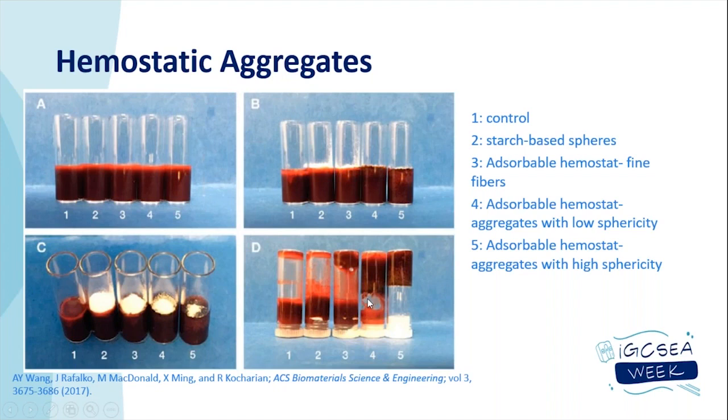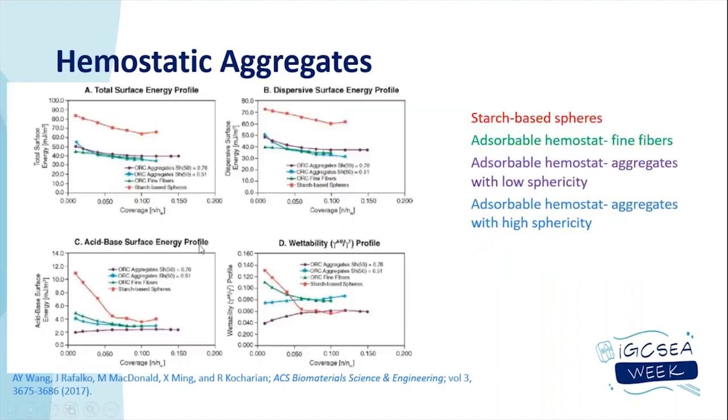So we want to look at the surface energy values of these materials, and it's a little bit busy. If you want the full details, here is the reference for this paper. But again, for these starch-based spheres, if we look at the total surface energy and the acid-base surface energy, the acid-base contribution is much higher. So these are very hydrophilic, whereas in the other samples, in particular the samples with high sphericity, we see a lower acid-base contribution, meaning that these might be more lipophilic.